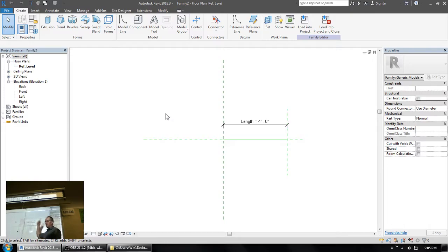Now, in the case of a parking stall, we want to slap those things together as tight as we can. So we will do parking with a second type array. Now, if we're doing something like a chair, the exact spacing between the chairs doesn't matter. What we want is that at the first click and the second click, we get a chair. With the parking stalls, if we don't get to an exact increment of the parking stall width, it doesn't matter.